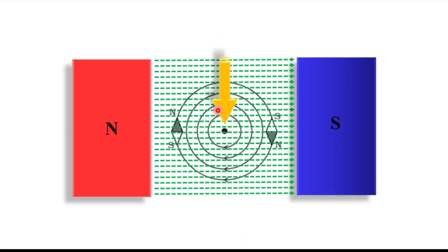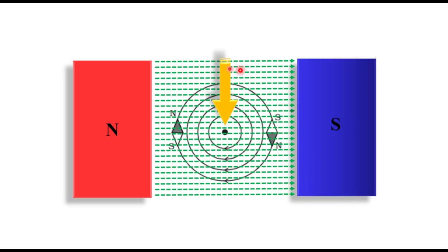So on this top part of the conductor, the interaction is a tendency to push down on this conductor. In other words, the top part of this conductor is being repelled by these lines of flux, but on the bottom side, it's being attracted. So both of these forces are equal, and they're in the same direction.